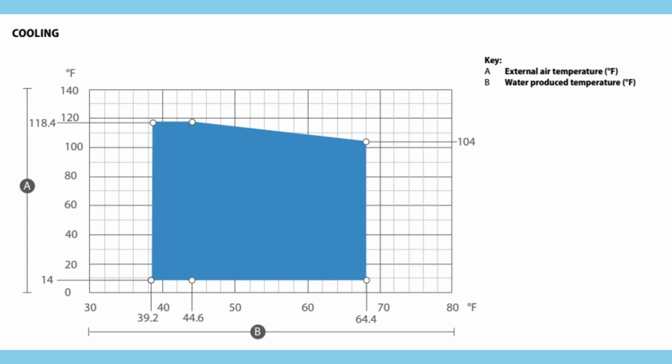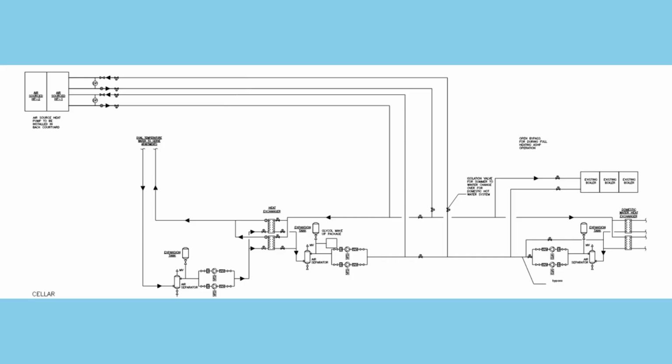Similarly, when switching to cooling, the loop must be cooled below a threshold. In summer, it's comparatively easy to switch the terminal load loop. If you run the terminal unit for a couple of minutes, there will be a heat loss on the secondary side of the glycol loop heat exchanger. Ultimately, the primary side loop temperature will go down so that you will have a loop temperature below 65 F to run the system. Ultimately, the mode changeover process takes time.